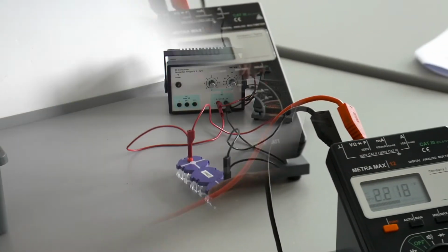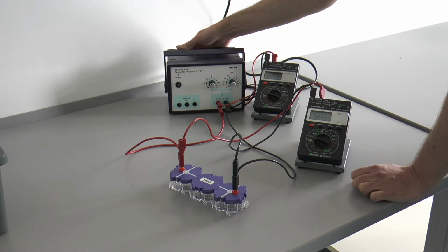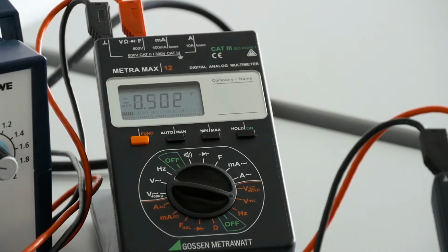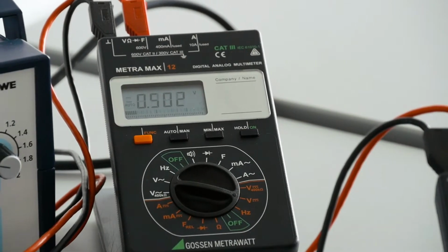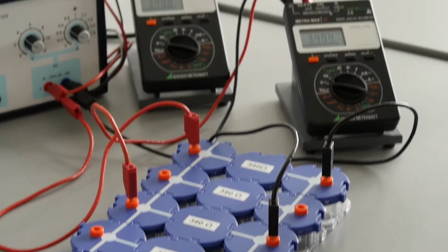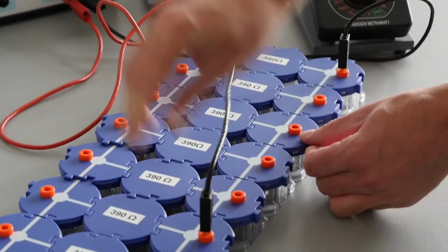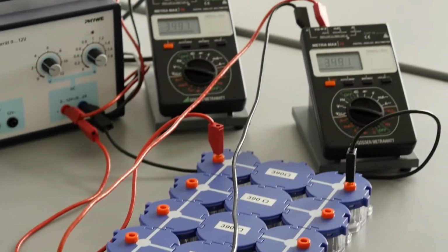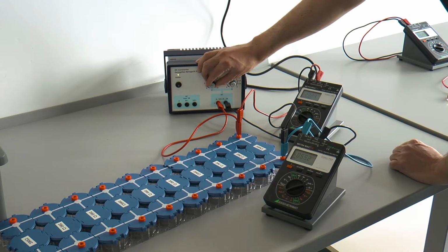In the second experiment, we again have a parallel connection of resistors. Each resistor is identical with 390 ohms. Each resistor simulates an open ion channel in a membrane. We start with one resistor and increase to 10. We can measure the voltage drop across the resistor network at any resistor since it is a parallel connection. The current is measured by a multimeter connected in series at the end of the network.